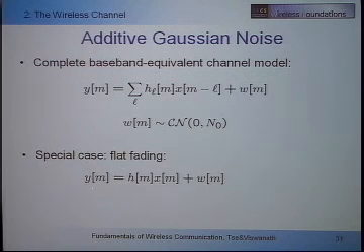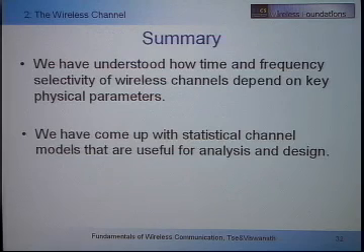Very often we'll focus on the flat fading model. In the flat fading model, remember, it's a single tap. Then I can ignore the indexing by l here and just call it h of m. m dictates, again, the time variation. Okay, so that's our model. We'll use this throughout the course.